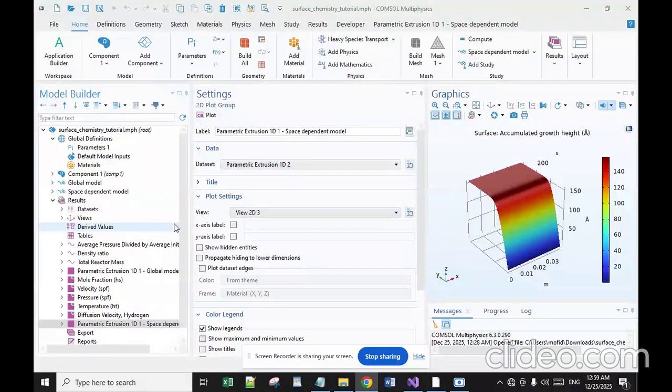Besides these intentional impurities, CVD oxide may contain byproducts of the deposition. TEOS produces a relatively pure oxide, whereas silane introduces hydrogen impurities and dichlorosilane introduces chlorine. Lower temperature deposition of silicon oxide and doped glass from TEOS using ozone rather than oxygen has also been explored between 250 to 500 degrees centigrade.